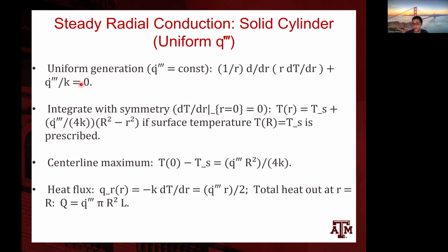The thermal conductivity depends on the temperature, and especially under irradiation, of course, there is material degradation because of irradiation effects. All of those defects that are generated will reduce the thermal conductivity. And we're going to account for that indirectly by changing the value of the thermal conductivity.